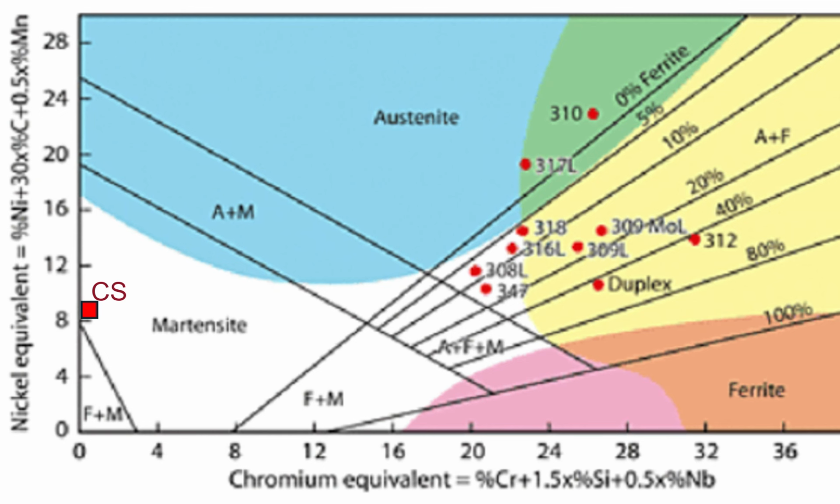So now if you go back to this, you find the 309 electrode or the filler is residing here. And as I mentioned, this 316 and carbon steel will be found somewhere here. So you will find this 309 has got a higher chromium equivalent and a higher nickel equivalent also.